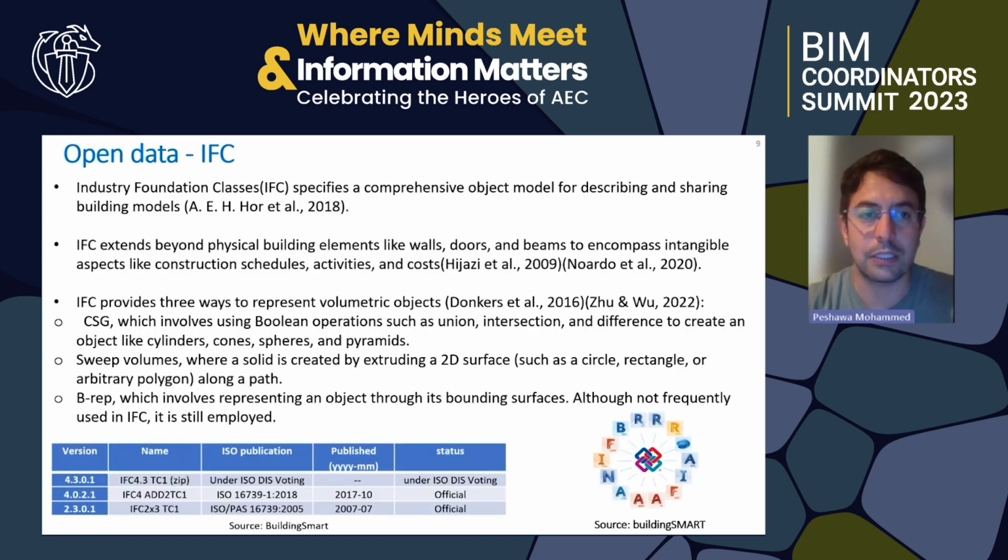So regarding IFC, Industry Foundation Classes specifies a comprehensive object model for describing and sharing building models, but also IFC extends beyond just representing physical building elements like walls and doors, but also it can represent construction schedules, activities, and costs. IFC provides three ways to represent volumetric objects.